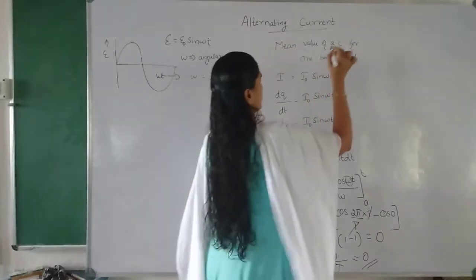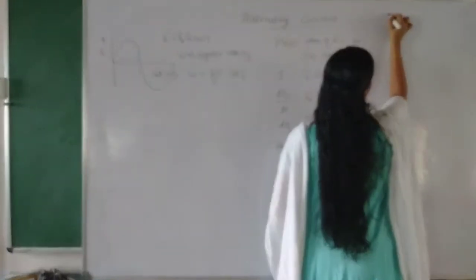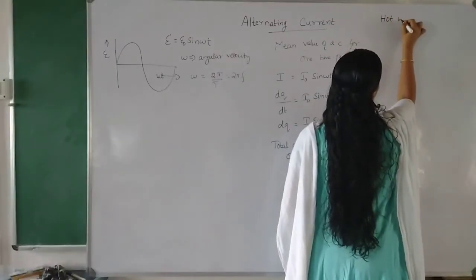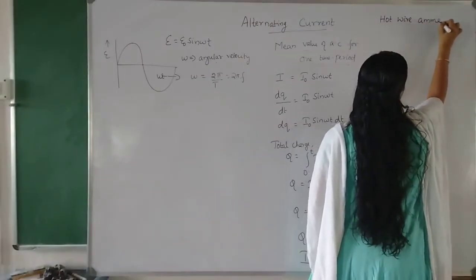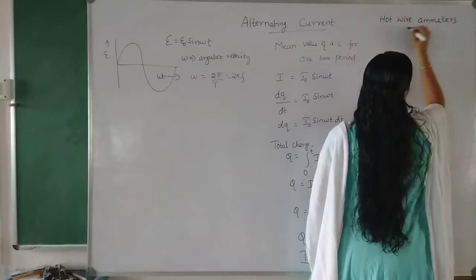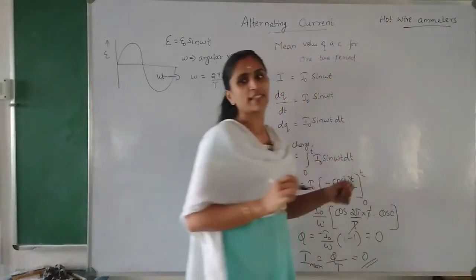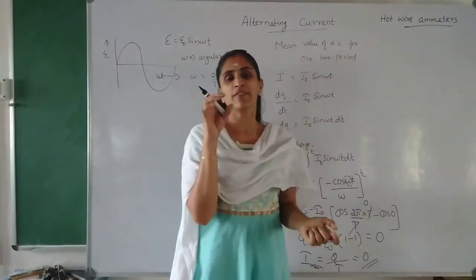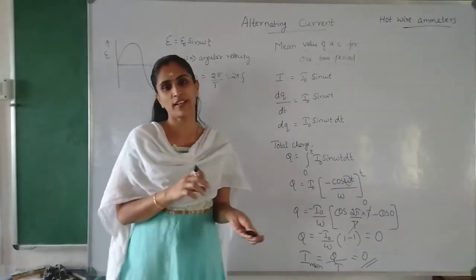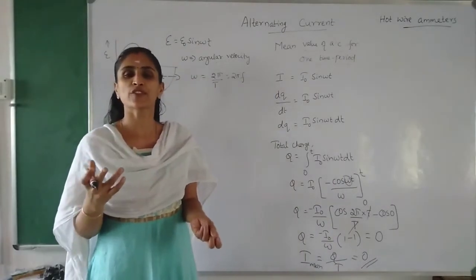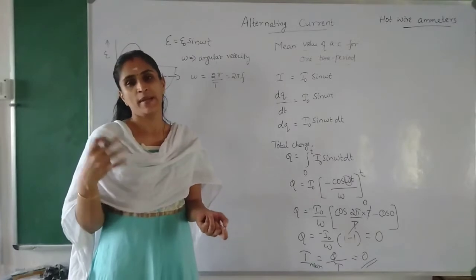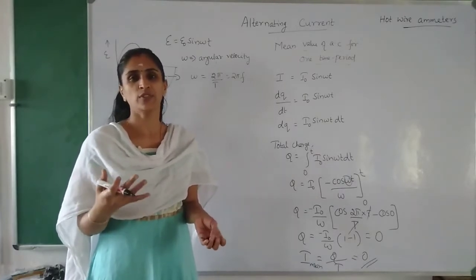Okay. We are using hot wire ammeters. From the word itself it is clear that hot means we are using the heating effect of current, and this heating effect of current does not depend on the polarity or direction of current.